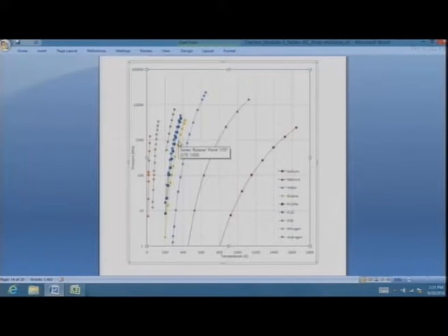The reason for bringing butane and all these substances together is that if you look at the thermodynamic properties of all these, they are somewhat comparable. And so one would say that I could have used butane as a refrigerant, or better still, substitute that hydrogen in butane or propane or ethane by chlorine or fluorine, and you start getting all these wonderful chemicals which were the refrigerants. And it was these wonderful chemicals that were responsible for ozone layer depletion.